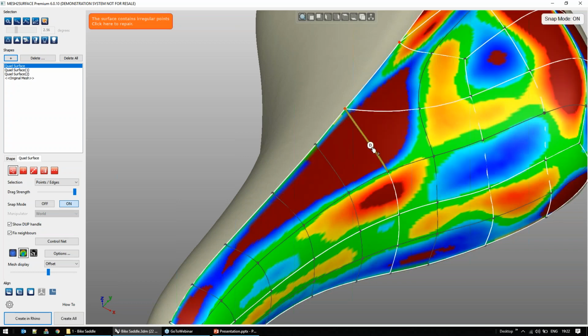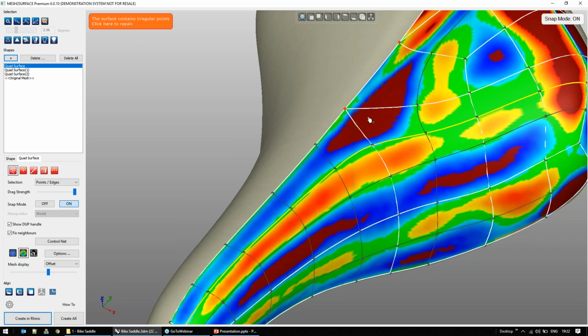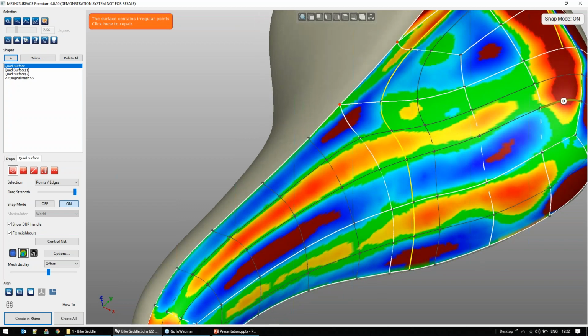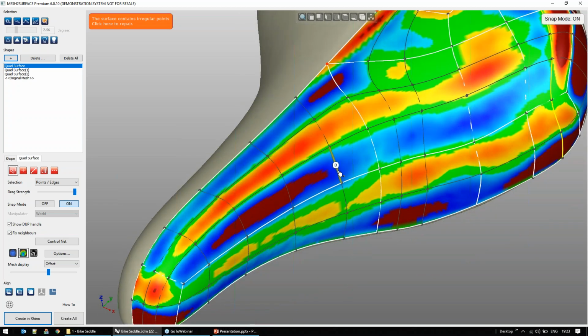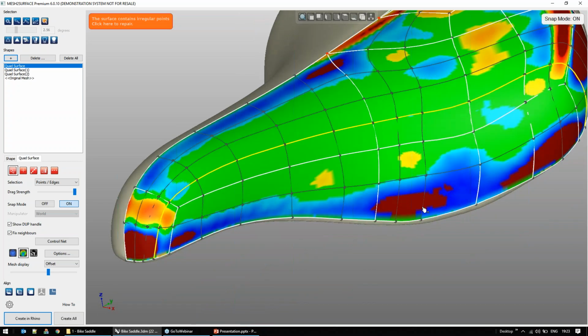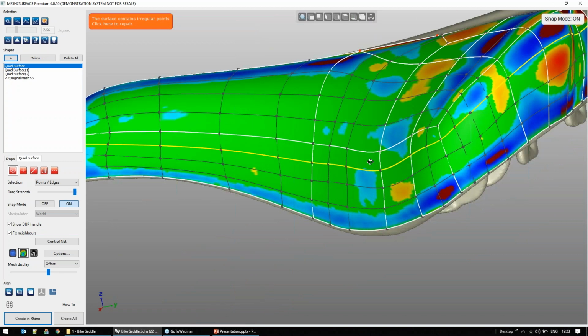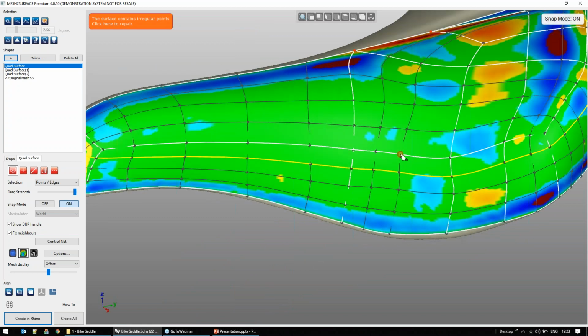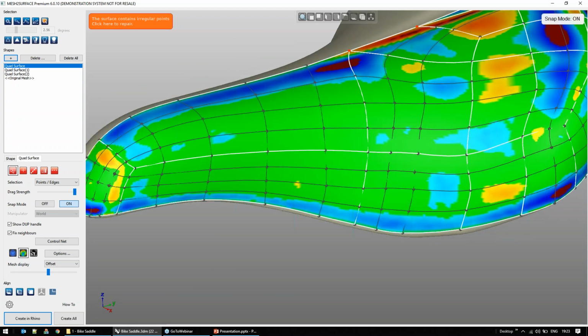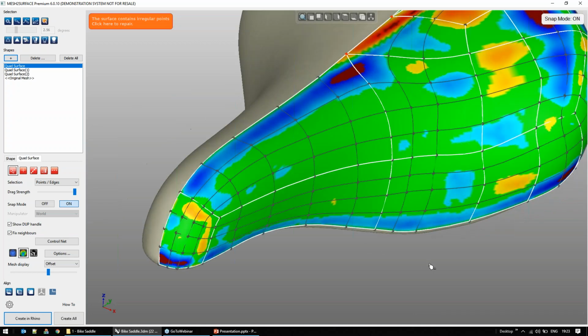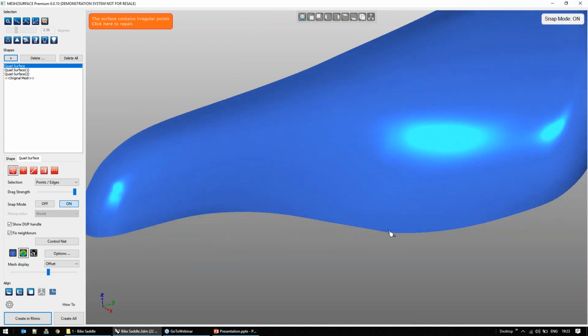Actually, I did increase the resolution. I just split this particular one. Then I can improve by selecting this one, pressing the S key, and this one. In such a way the user can control the quality of the mesh, how close it can be to the surface. Please note that increasing the resolution will get close to the mesh, but it will actually capture all the defects and all the problems which come from the inaccuracy of the scanner. So as you see, this will be my result.